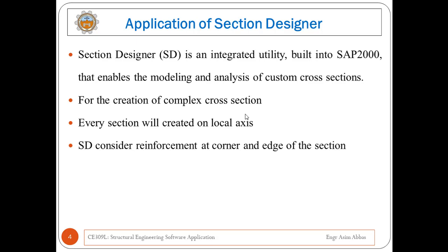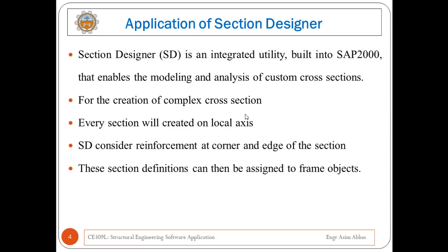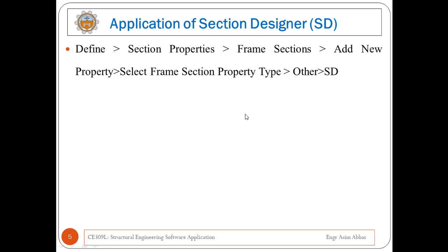And you can also draw reinforcement inside the cross section where required. Once any section is designed using the section designer, you can then assign it to any frame object.